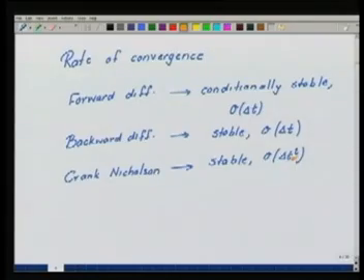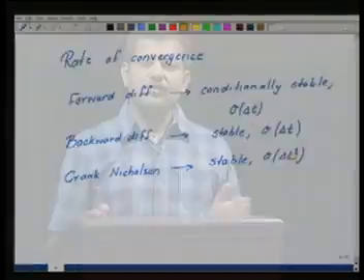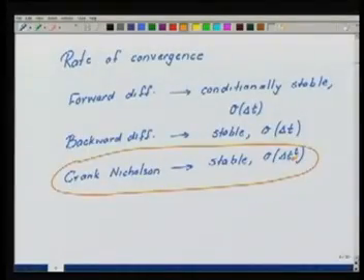So what we expect is that with larger time steps I'll get more accurate solutions if I use this one. That's what it means. Just like when we used higher p elements, with a coarser mesh with fewer unknowns, we got the desired tolerance because the rate of convergence increases. So these are similar approaches, similar philosophies, which are adopted in both spatial and temporal solutions.